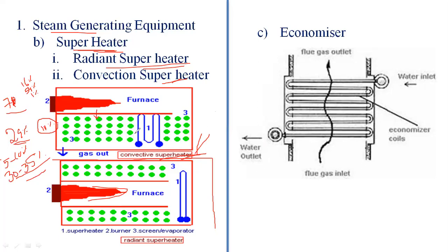In the convection type, the commonly used rising characteristic means the temperature of the superheater increases with increasing steam output. Here the superheater removes the moisture particles and raises the steam above boiling temperature. Due to that, the efficiency is increased by up to 5%. The superheated steam drives the steam turbine at high pressure and temperature through a valve. After that, the valve feeds the steam turbine. Based upon the demand, we adjust the valve controller.